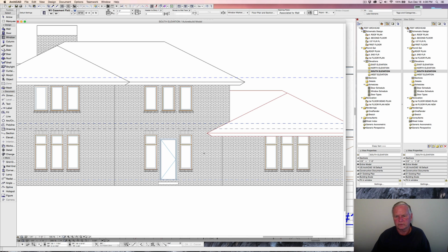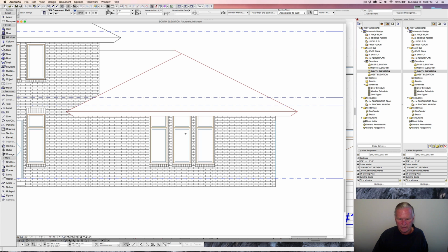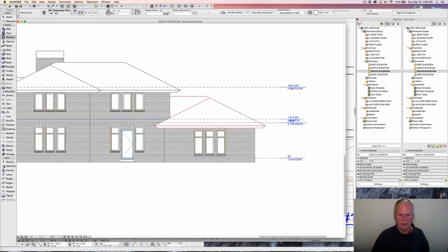My 3D view is going to show correctly. And I might adjust the height of these windows. As a matter of fact, as I'm sitting here talking about it, I think I will pull those down because they're set rather high in that garage. Let's bring them down a foot. Control D, drag them down, D 1 foot, and we'll get that look from the outside. And frankly, I like that better. That works just fine for the garage. So we've got to remember to do that for the back. And if you're like me, when you're thinking of something, you should just go ahead and do it.